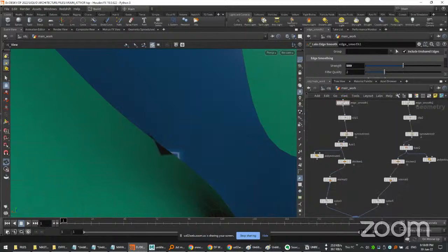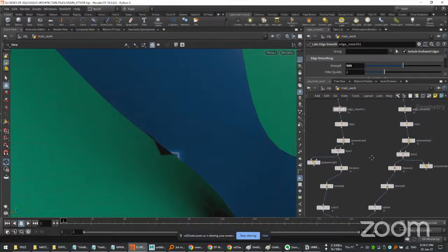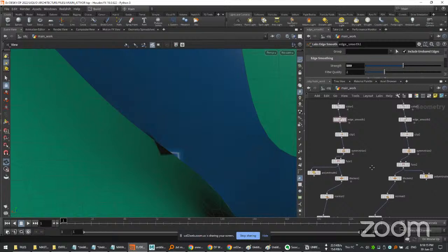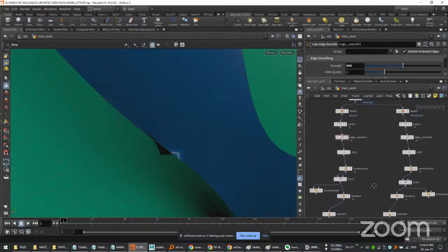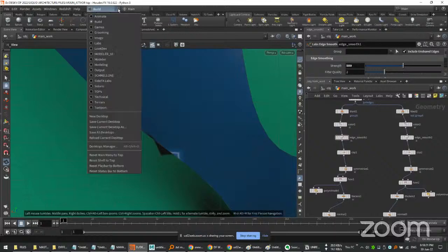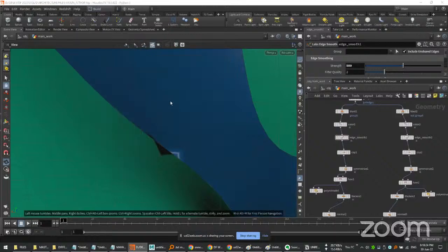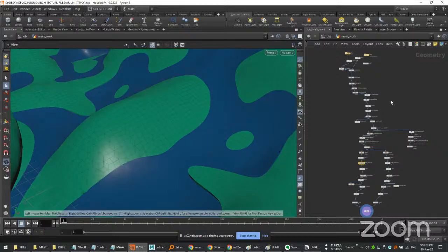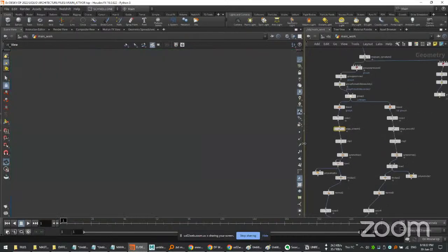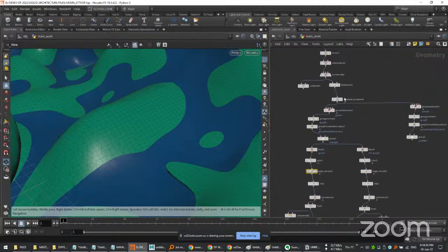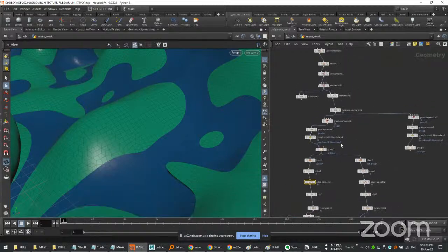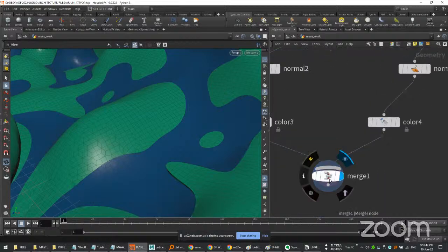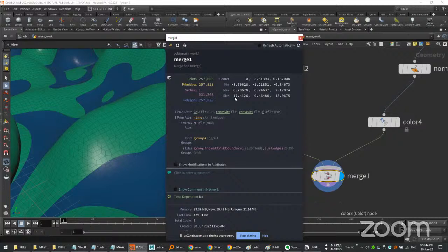Another thing that you could try is increasing your subdivision. Of course, it will take more time to calculate, but that could be a solution. Yeah, but one way to control it is by using that smooth neighbor option. And another thing that you could do is subdivide your tree one step more and see what happens. Even though I don't know how many points you have right now on your particular model. I should check. Be mindful. Yeah, you can press the I button. Oh, okay, you can subdivide even more.